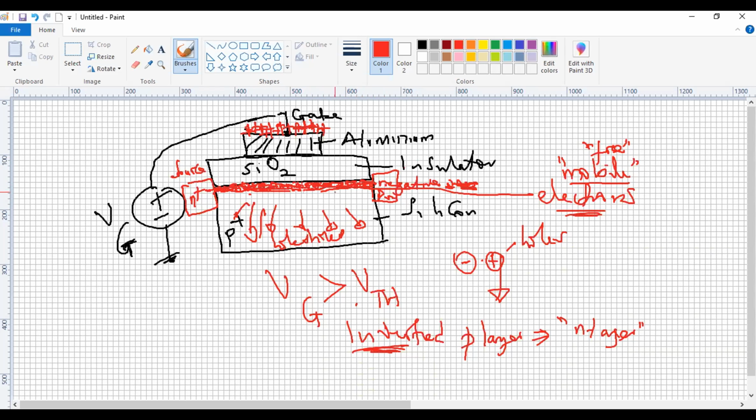So, but this would be for the case. So this is what I want to do. And this is a situation for the low signal MOSFETs. So we've seen with the other one, with a power MOSFET, this side will be lightly doped, but at least you can see what you're trying to do. And I'm assuming you've seen this before, so I don't actually have to spend as much time. It's more of a review since you've seen this before. So I create this thin channel through which electrons can flow.